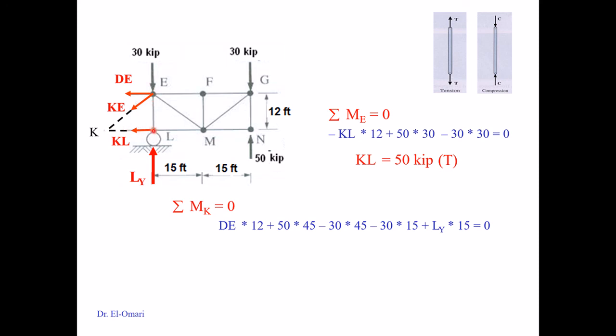All right, please, it's only the distance that is perpendicular to the force. Many do the mistake and would take the 12. The 15 is the correct distance, and it's rotating clockwise, so it's negative. And then finally the LE that we just found, which is multiplied by the 15 and rotating clockwise.